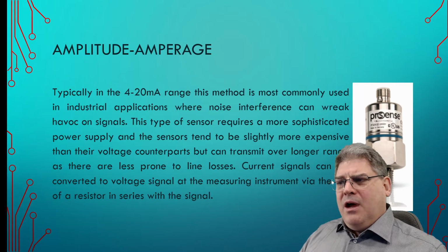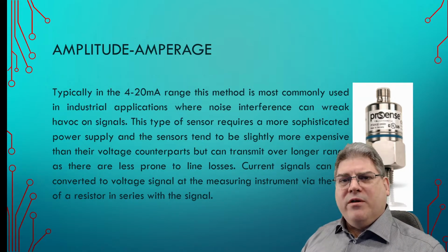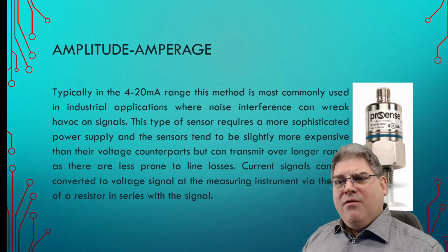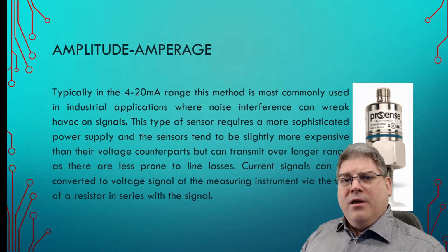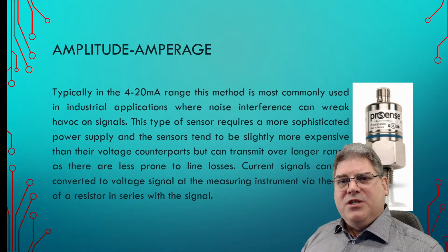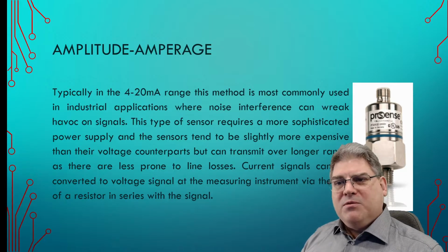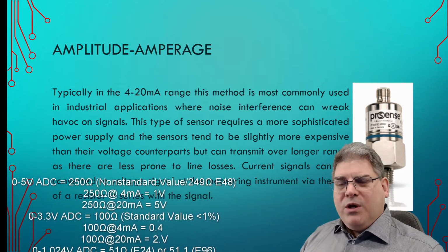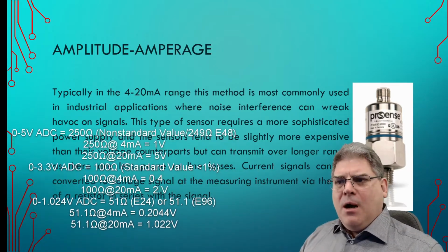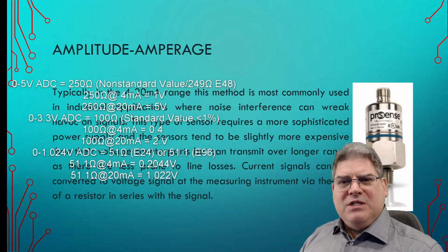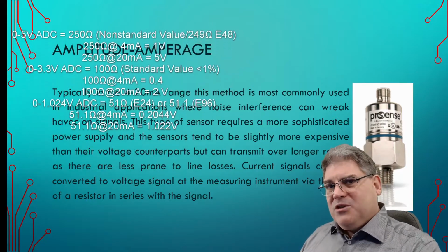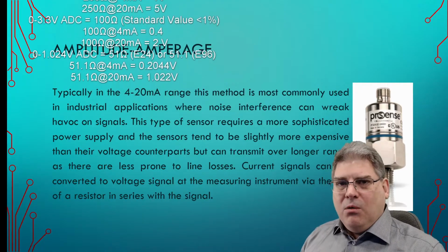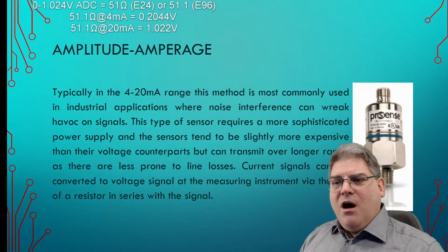So as the pressure increases, the current increases as well. And so we have a resistor called a sense resistor that's on our circuit board, and this device will adjust the voltage to give it the exact current that it wants, somewhere between 4 and 20 milliamps. And 4 is a great number. This actually works out very well when you pick that current sense resistor. But it means that if you don't see that 4 milliamps, you know that there's a problem with the sensor or the wire. So if ever you see 0, you have a problem. So it has a built-in fault detection.